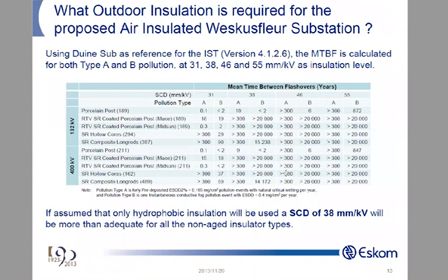Out migrates. These low molecular chain silicons migrate to the surface, and they start encapsulating the pollution particle. All around. Now remember, these CH3s don't like a polar thing. So what do they do? They all go outwards. So now what is around this polar thing in the middle? All these CH3s, these methyls. What are they? Hydrophobic. So there you got a hydrophobic particle now. And that's how low molecular weight silicons migrate to the surface, encapsulating the pollution particle. And that's how they migrate into the actual pollution layer.